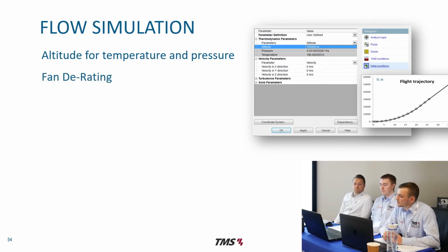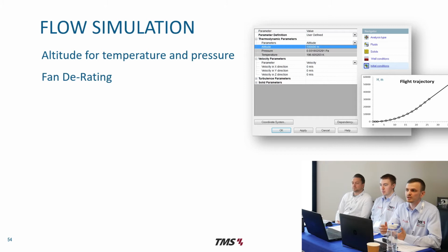We also now have the ability to use fan derating in there. Now, as most of you might know, if you're used to working with fans, they don't often actually work at maximum capacity. The reason being is we want to try and prolong the life a little bit, and we even want to get rid of any noise that's coming from them if we run them at maximum capacity. So now we can take this into account with our simulations as well. We can now incorporate this derating factor in the setup.